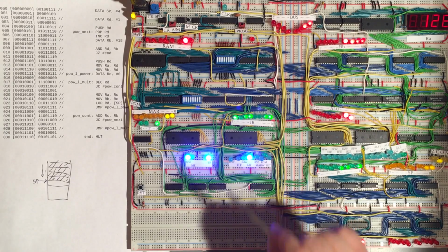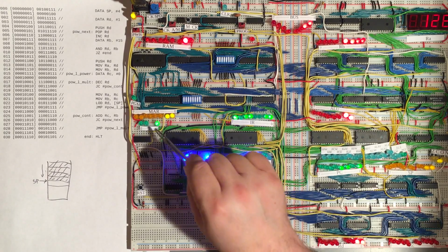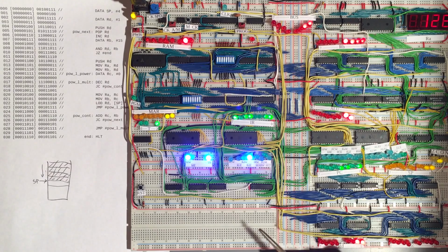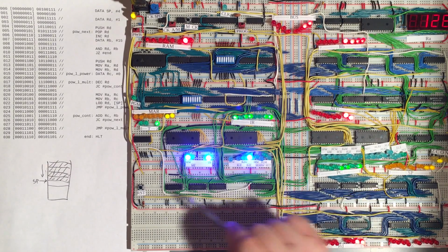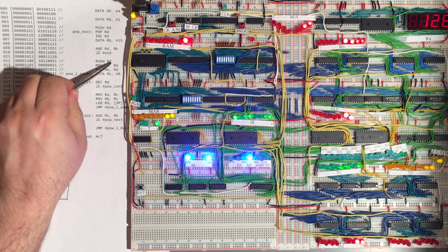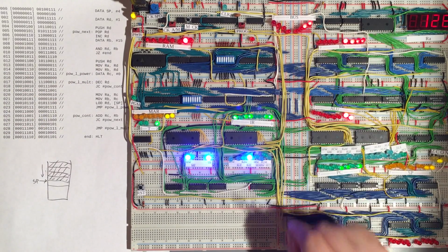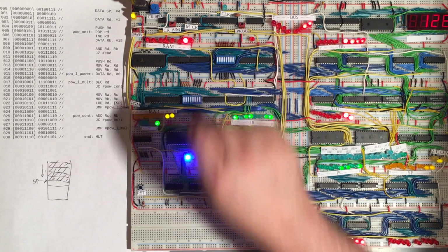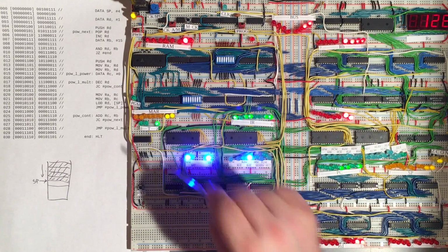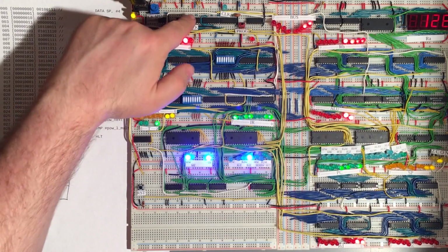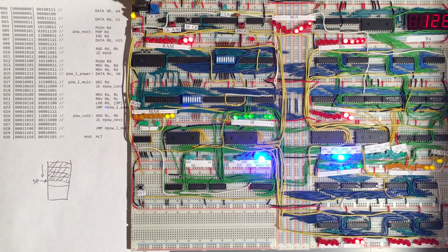And now we're ready for the final microcode on T4 of this push instruction, which is now to write to memory using the input from the register, which we are pushing onto the stack, which is the D register. And so this 3 is now on the bus because it's enabled, and that will be written into RAM at address 3, which is the new stack pointer address. And there we are. And so that concludes the push instruction.